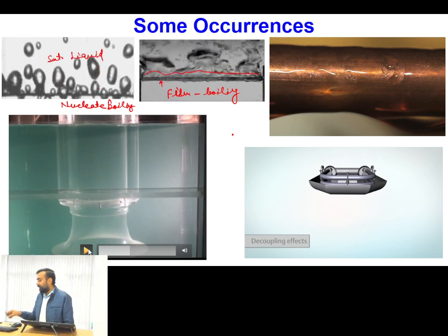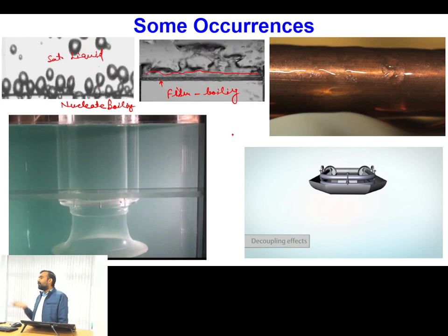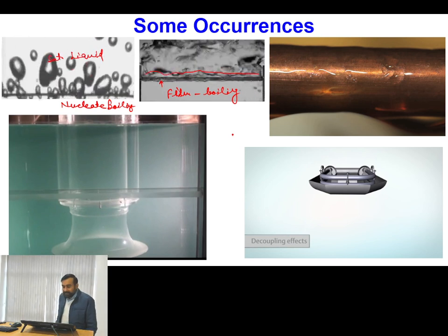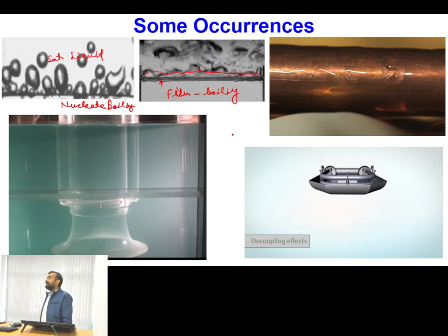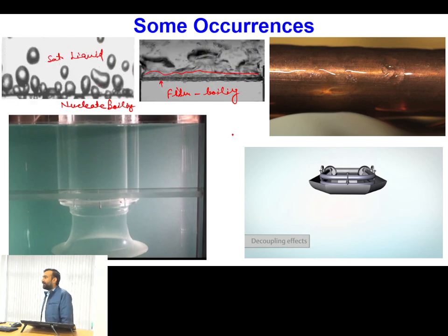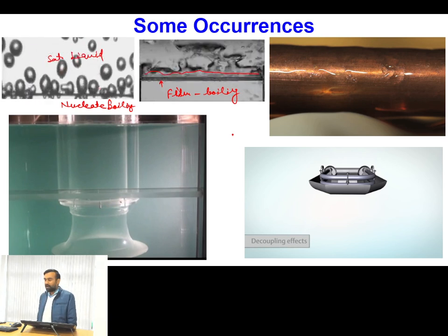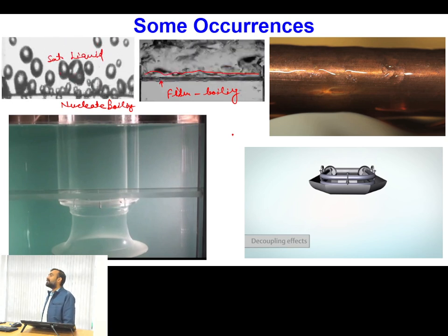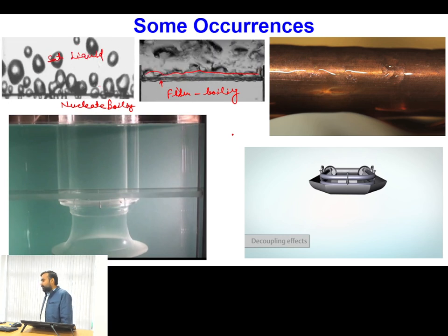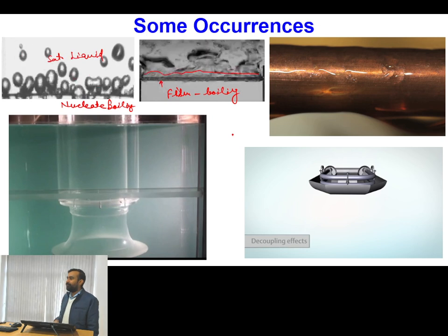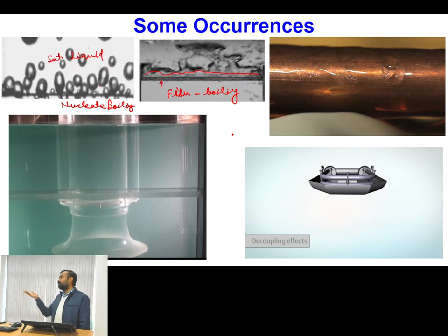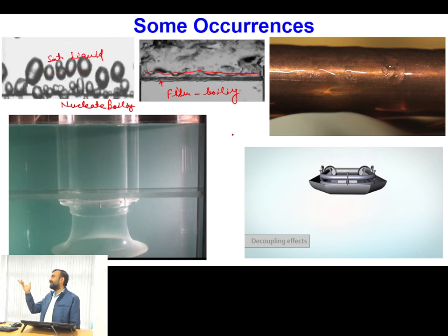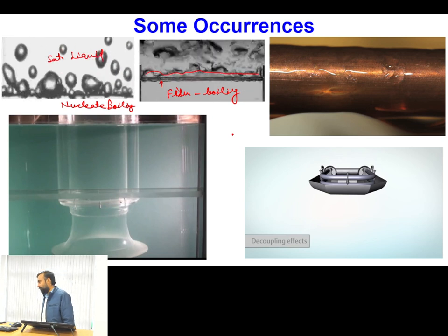Now, typically our pumps are designed only for operating with pure liquids. Okay, and if the air is going into the pump, then ultimately it can lead to cavitation and erosion of the pump blades, which will be ultimately leading to decrease in overall lifetime of the pump. So this entry of air may not be bothering a household person, where in our house we will be operating the pump, say in a day only for half an hour or 1 hour.